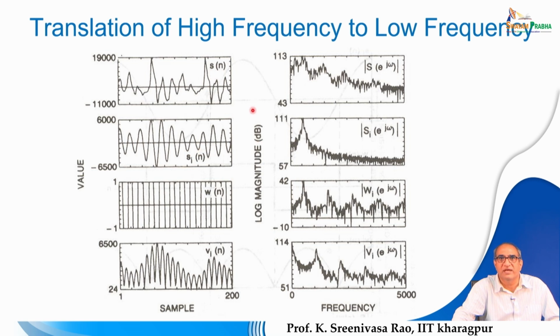And if you look at the corresponding spectra, this is the spectrum of a normal speech signal, and this is the spectrum corresponding to the narrowband speech signal passed through one of the filters. Now this has to be shifted towards the lower side. This is the case where the pass band is situated around 500 hertz. The same way, if you take a filter at the other extreme end, you can see a similar characteristic at the high frequency end.